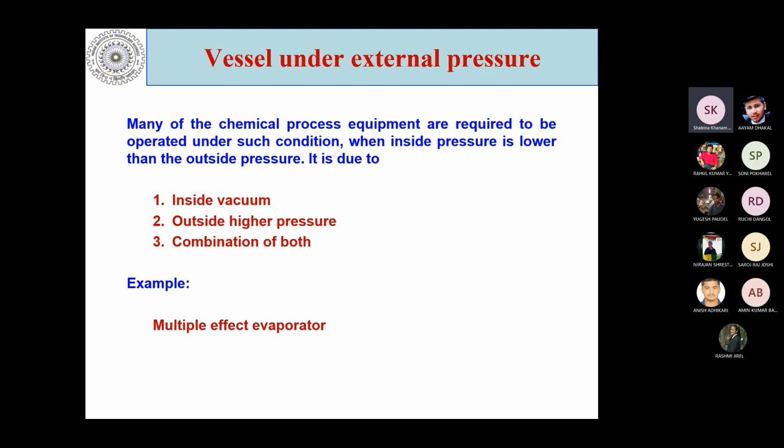You must all be aware of the operation of the multiple effect evaporator, that the whole system is operated under vacuum. Whether we have one effect, two effect, three effect, whatever the number of effects, at the last effect we have the vacuum pump which creates vacuum in all effects.